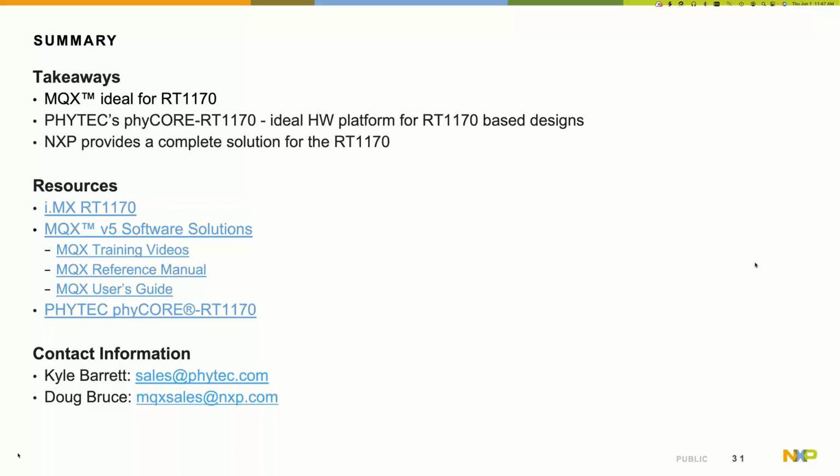Next question, this is for Doug about MQX. Does MQX RTOS support POSIX APIs? And if so, please list the available supported APIs. The API is POSIX-ish. It's not 100% compliant with POSIX. For people porting legacy application code that was written for truly POSIX-based interfaces, we have a wrapper layer that goes on top of MQX, and it converts, I don't know if it's absolutely every API, but a great number of the APIs to MQX. So your application code would think it's running pure POSIX, running on top of MQX. That's a separate add-on. It's not normally provided with the package, so reach out to me and we can talk further about your requirements and what this wrapper layer supports.